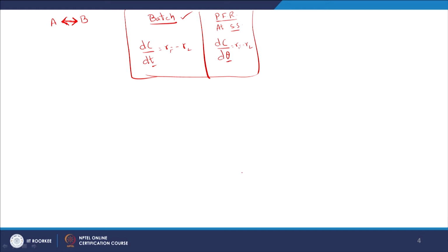So moving on, we have the next case, and what is that? I guess that's the CSTR. Let's look at how to apply this CSTR case to your reversible reaction now. I'm in general not good with mugging up formulas, so let's see again, for the purpose of refreshing our memories, how we get the mass balance for a CSTR. What's a CSTR? A continuously stirred tank reactor. You have flow coming in, you have flow going out, and you have concentration coming in and concentration going out.